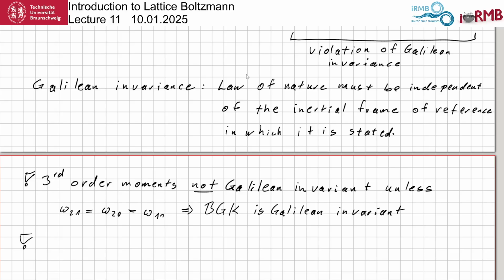So even in the case of a non-discretized or perfectly discretized velocity space, we would still not be Galilean invariant in MRT. So this is very important to notice, because you can always say it's discretized, but this is not the reason for MRT not being Galilean invariant. This means that the violation of Galilean invariance in MRT is worse than necessary from the perspective of the discretization.